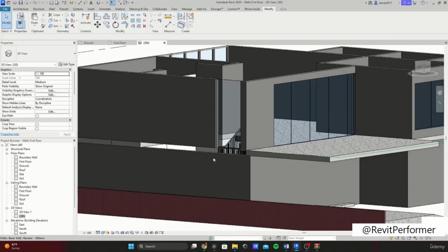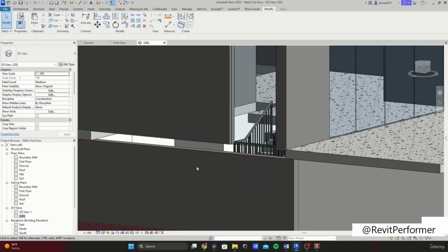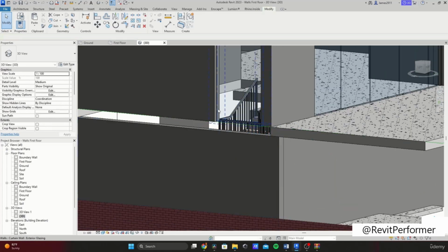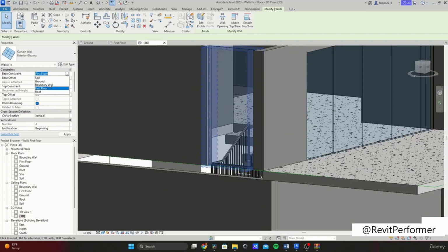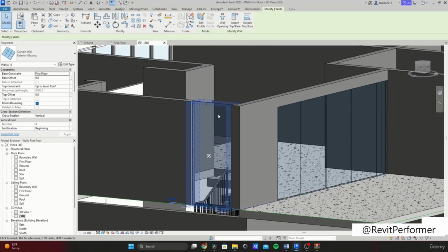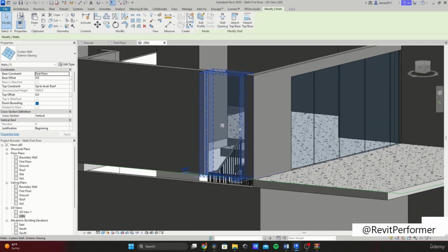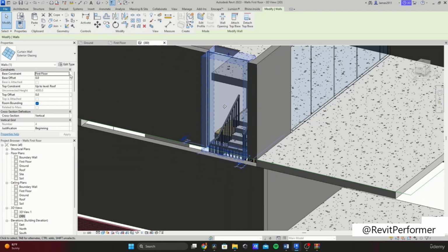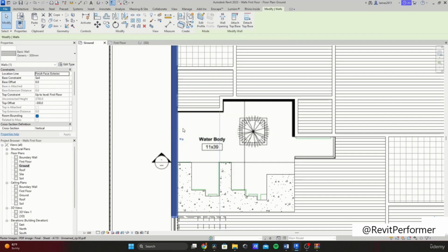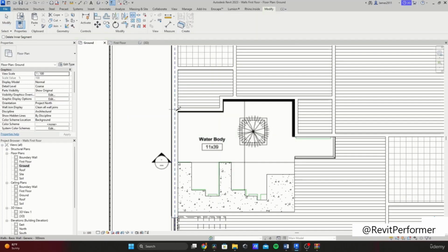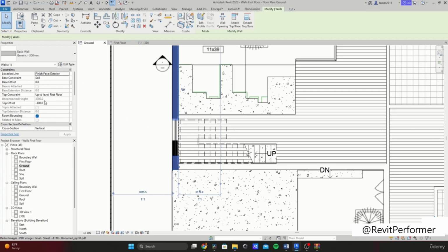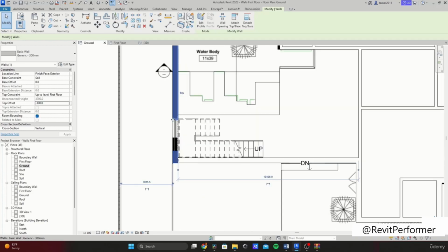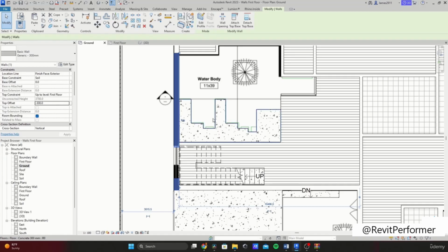As you can see, we have some cleaning up to do. Now, I also want to extend my wall from the curtain wall that we've created behind my stairs. I want it to be on the ground floor for it to be extended. Now I'll select this, and I'll go into my first floor. I'll click on S1 and drop it right over here, which will split it. Now I split it at this spot.